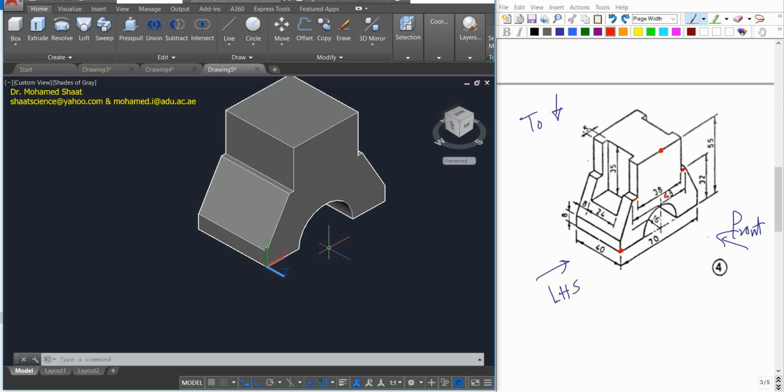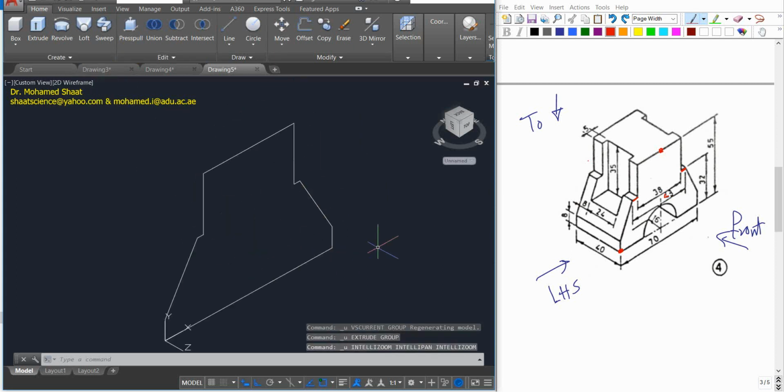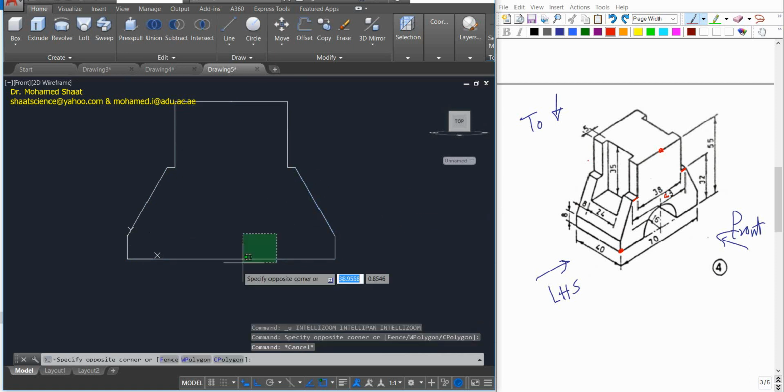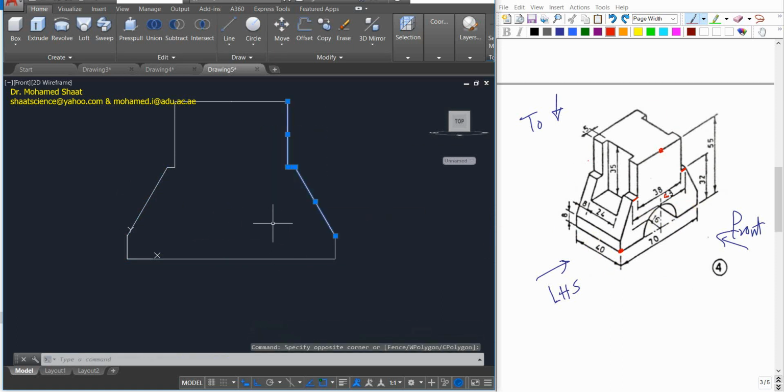But as you can see, we took like 2 steps, and this is gonna take more time. Can we do it in one single step? We end up with typically the same shape with one single step, yes, by using something which is press pull. So how it works, I'm just gonna start over again, okay? So this is the shape without union. I just draw this shape, right? So the first step, your objective is just to draw the entire shape. Then, before you do union to the shape or doing extrusion, your objective is just to draw the circle. And from the midpoint, the circle should have a radius of 16.